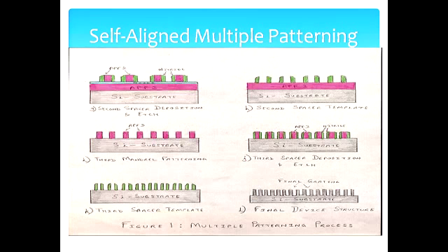So then comes the third layer. Again, in the same way, silicon nitride is deposited. The number of lines keeps doubling every time I do a mandrel, spacer deposition and etching. When I etch away the second mandrel, this is what I get, the second spacer template. This is now 4 times what was the original. This is the final mandrel, and these are the final spacers, which are now 8 times what was originally defined. These define the final lines which go onto the silicon substrate over here.